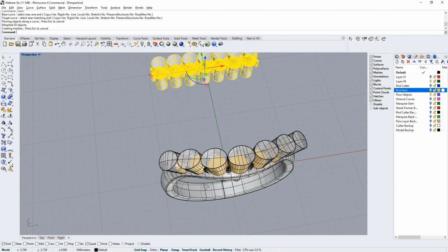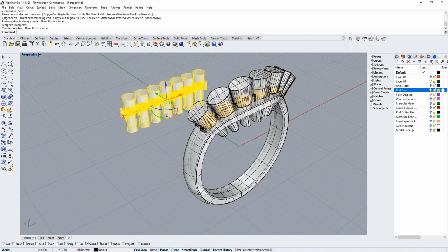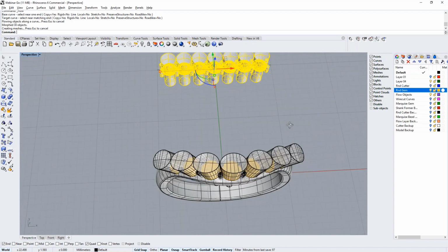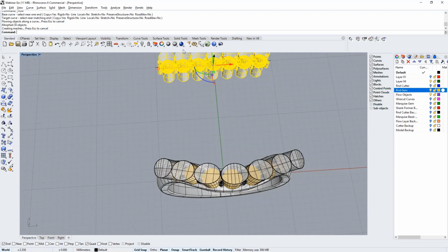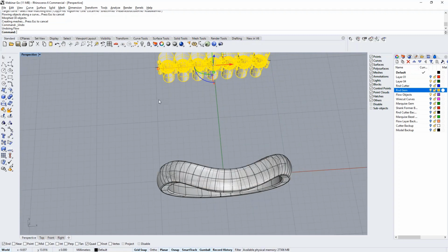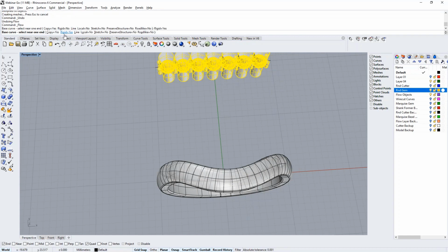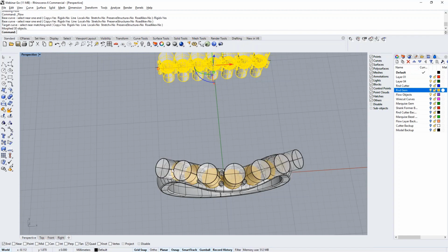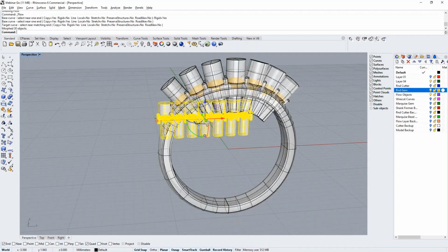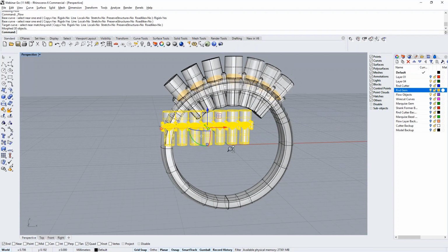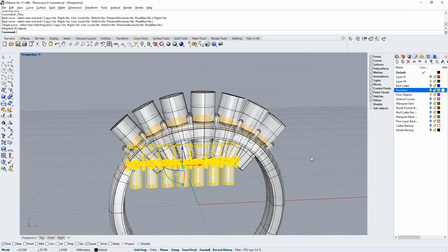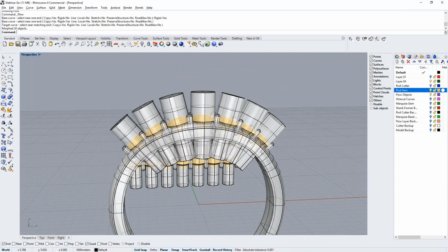Notice, because I want to show something here about that selection, and this ties up a lot of people. Notice how it stretched these objects along the curve, which isn't okay because our stones are round, right? So we're going to back off of that. We're going to reinitiate that command. And this time, see right up here, we're going to say rigid. So we're going to keep these objects rigid. Base curve in here, and look at that. Beautiful.